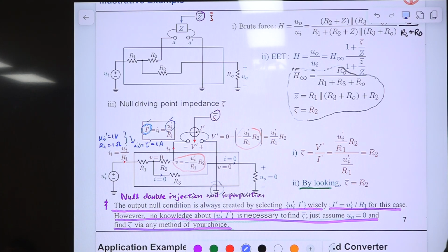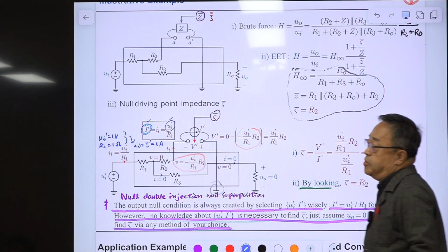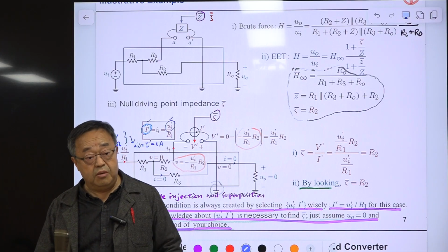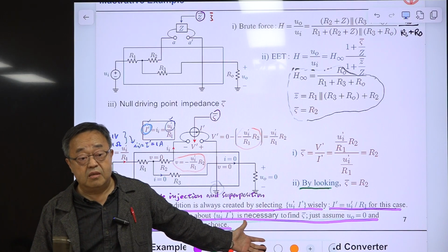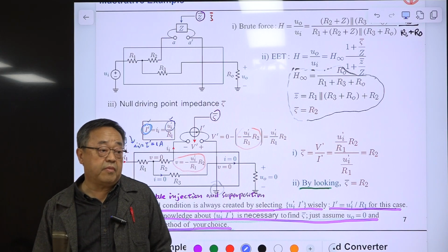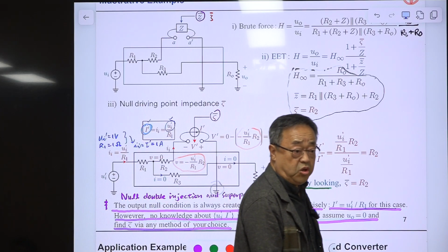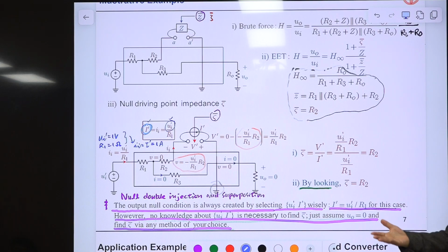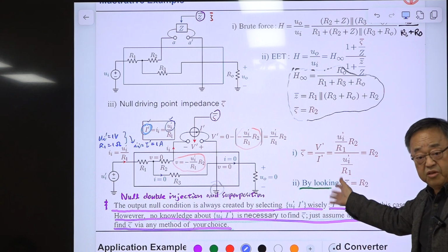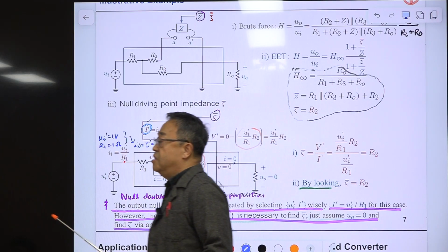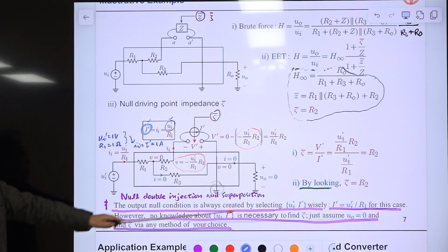So the formal way of proving the Thevenin's form is the use of the superposition principle, very similar to this. It's not easy to figure that out. So many textbooks and most professors don't mention that. Where does that come from? It comes from the superposition principle, very similar to this kind of thinking, this kind of reasoning. So this is very important.